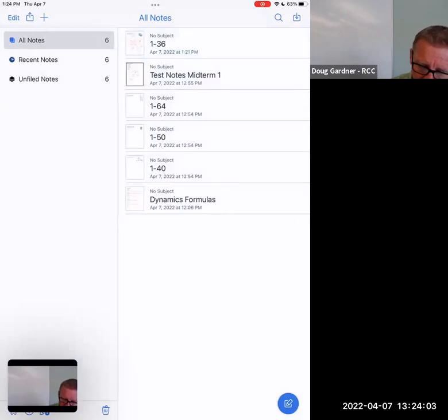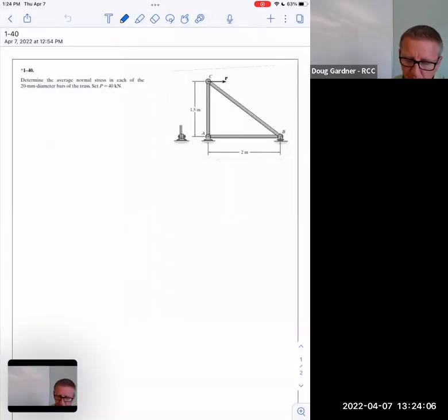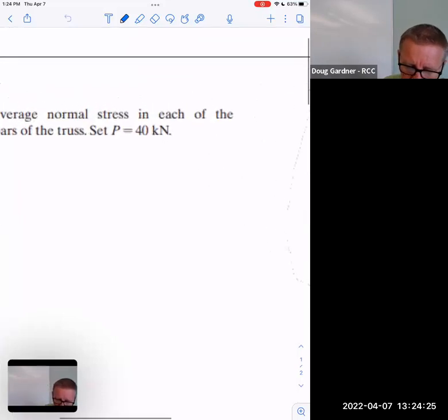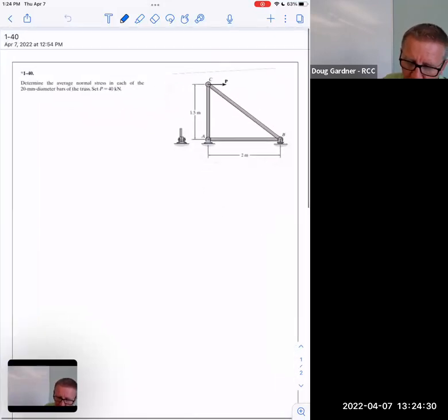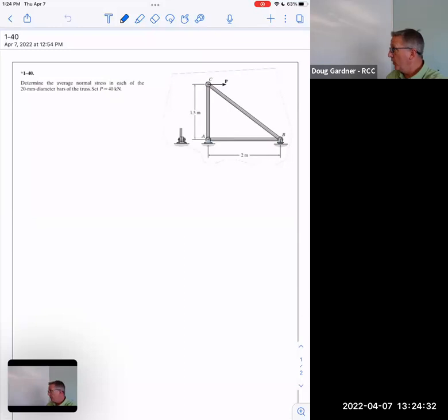Let's do something slightly more challenging. And this is the same question, actually, but I just have to work a little harder to get the 6,000. Last time they told us, oh, it's 6,000 pounds. Awesome. Well, here I'm told, and notice this is a Newton problem, they said P is 40 kilonewtons. And so incidentally, did you notice last time my method worked really good? Because when I divided 6,000 by 76 or whatever that number was, it came out a reasonable PSI number. Like it was kind of good that I did that.